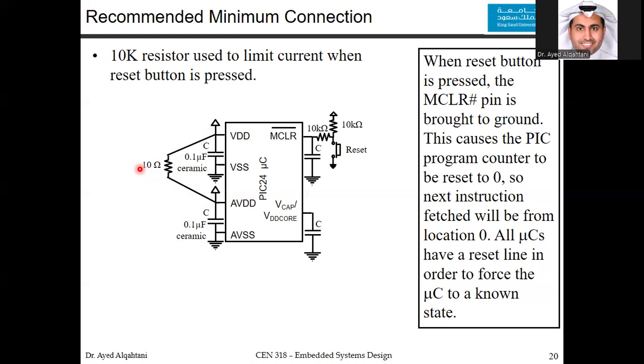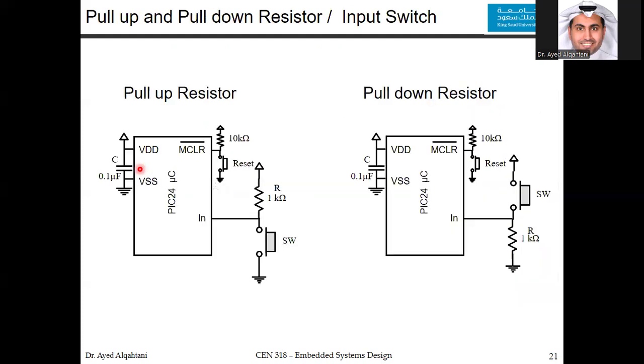Now, next we will move to the switch options and also the LED options. So here in the switch, we can connect it as a pull-up resistor. The switch obviously will be connected to an input to the PIC24. You want to input a value.